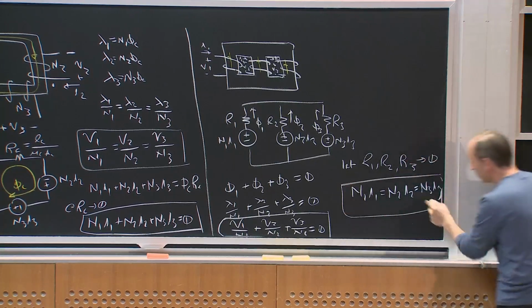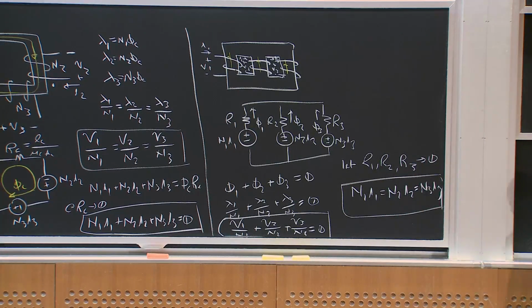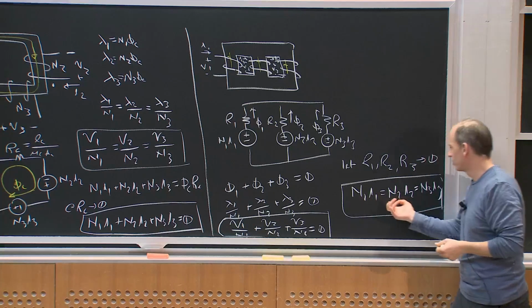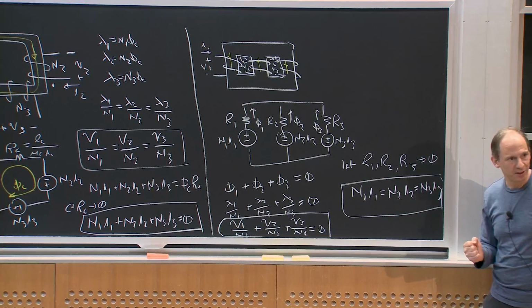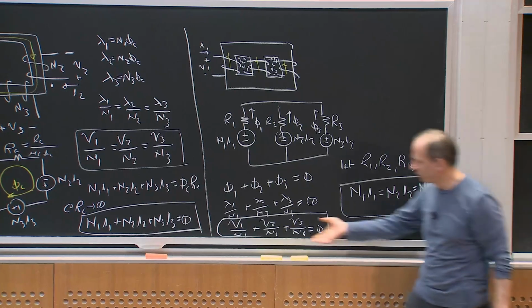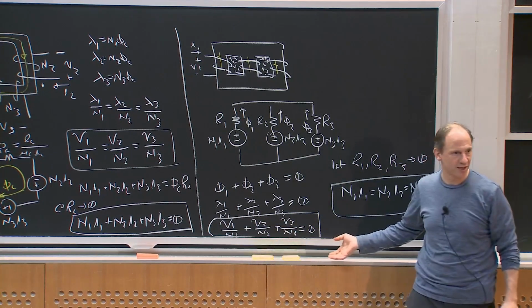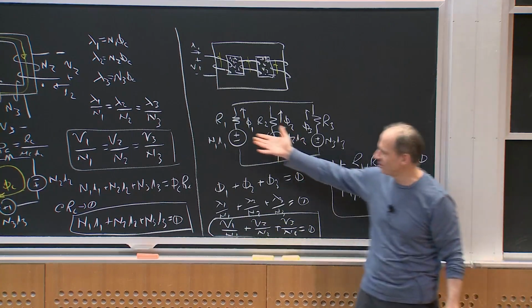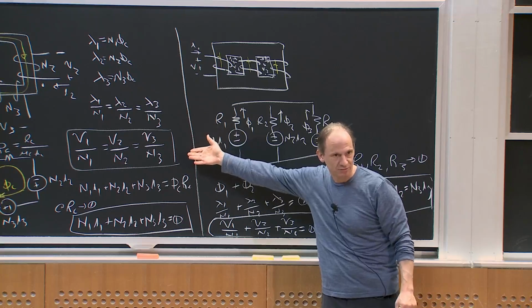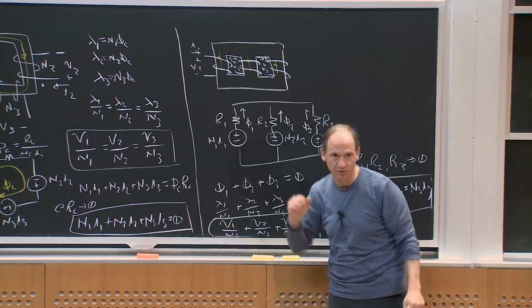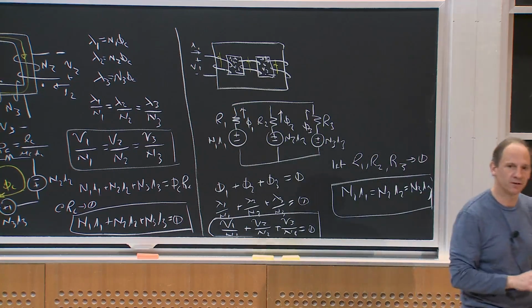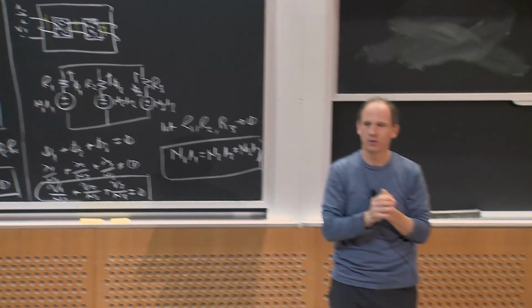Okay? So in this parallel wound transformer structure, or parallel magnetic paths instead of series magnetic paths, the currents in the windings scale equally, ideally, and the sum of the scaled voltages adds to 0. It's exactly the dual of the series structure. In fact, these are structural duals, between series and parallel. So you get dual relationships between voltages and currents.